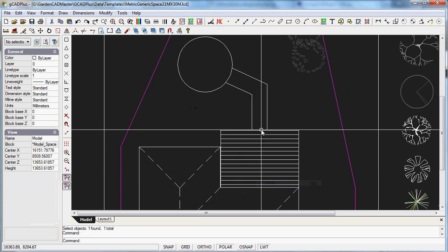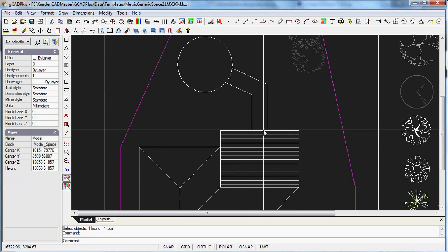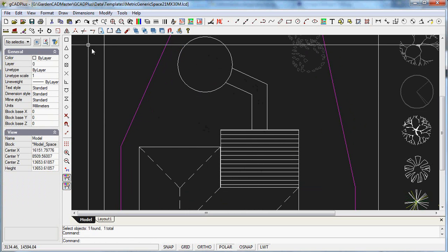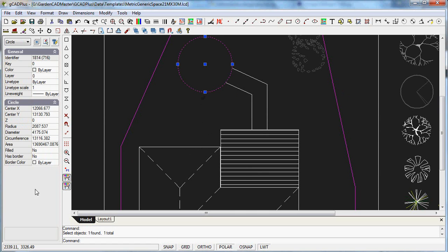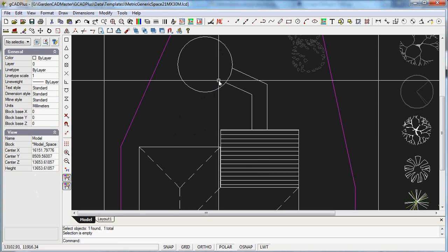So now we have a path leading from the midpoint of the decking area through here, and you might well hatch that zone through there and even hatch the circle. There'd be no difficulty in picking that circle, which I forgot to put a nice diameter. It's 4175, which a tradesman could work with, but I might want to offset a little bit to the inside.